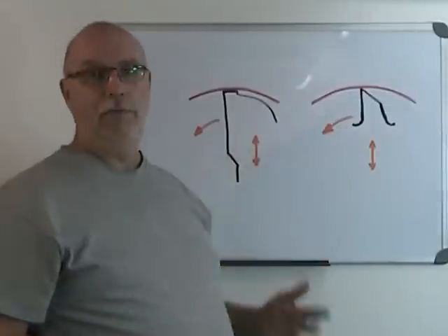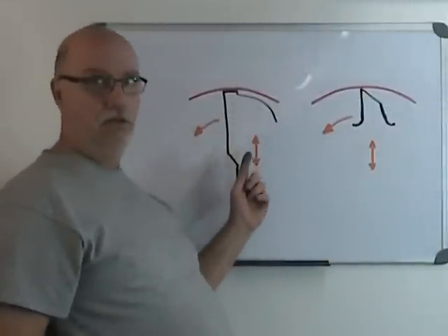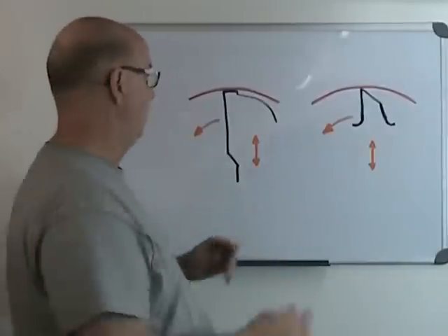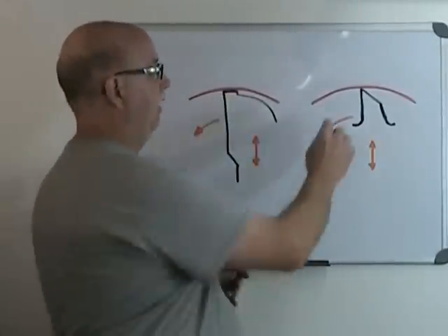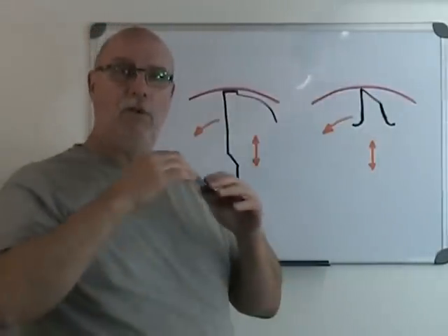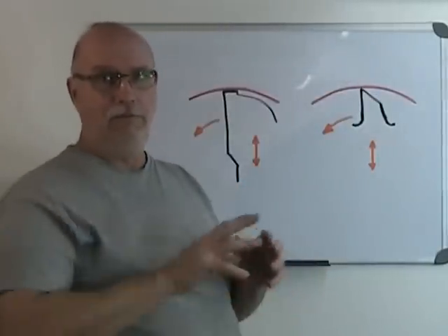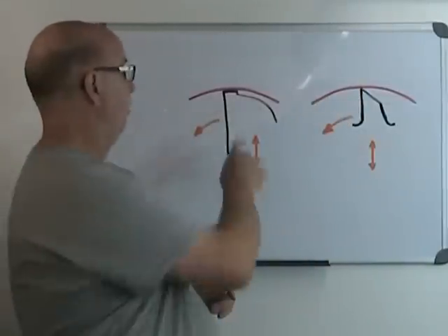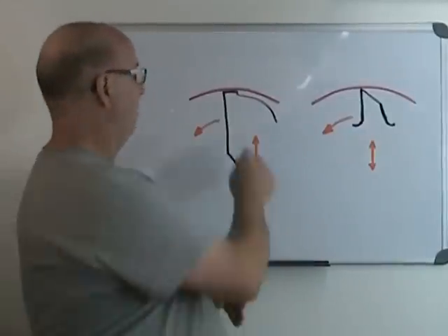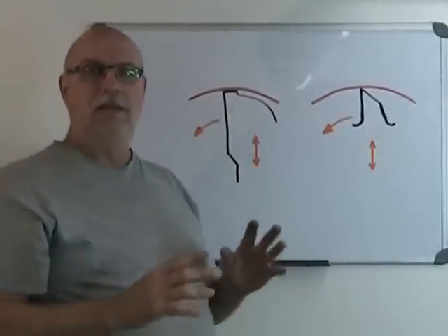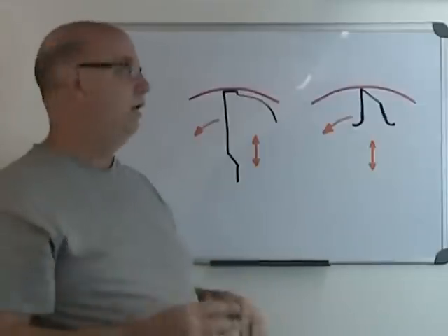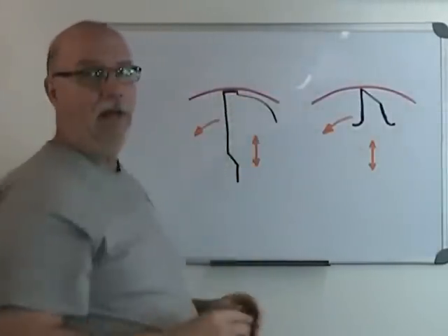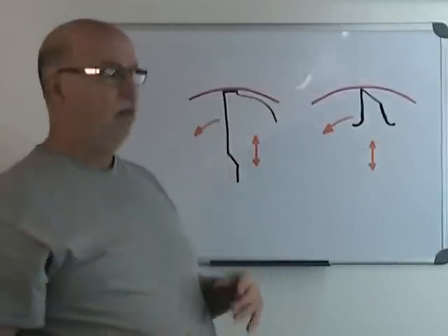So we have here a representation of a drill and a reamer. And what we're looking at here is the margin in the drill's case and the edge of the cutting lip, the one that is all along the flute of the reamer, and we can see that this one comes to a point whereas this one doesn't. Now what's the difference? The margin on a drill is the diameter of the drill. It has no clearance. So if I took this margin and stretched it out all around the drill, I would get a nice circle. There's no clearance.